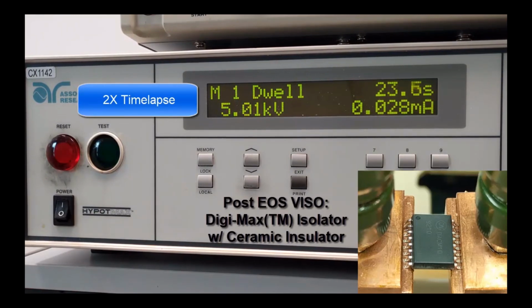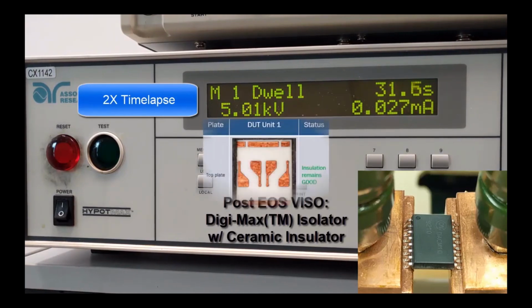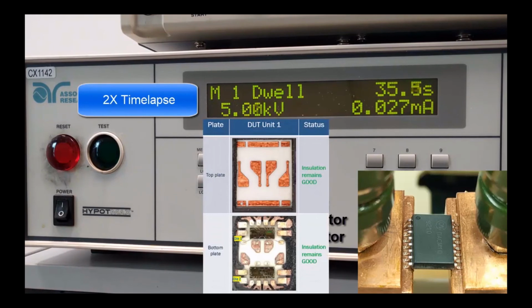Similar to optocouplers, in the Digi-Max technology, if the IC is damaged, the device may no longer function electrically, but the off-chip insulating materials are protected and continue to provide reliable isolation. This fail-safe operation is ideal for safety isolation in high voltage applications.